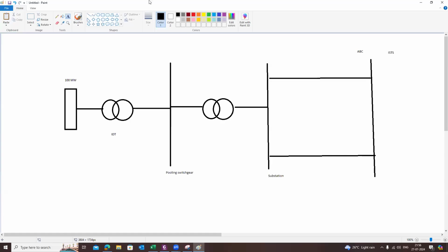That's precisely why ETAP is for the industrial network, which has a limited number of buses, whereas a utility has some thousands of buses, which makes it difficult to run the load flow analysis. Even if you want to analyze the loading of the network for a particular zone or region, that will be difficult in ETAP. Yes, in ETAP there is a possibility to get load flow convergence for a country or utility network, that is possible, but it is still difficult to analyze the condition of the network for a particular zone or region in ETAP.